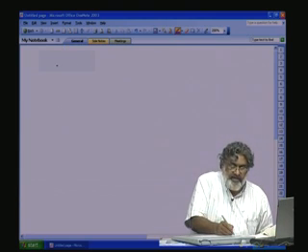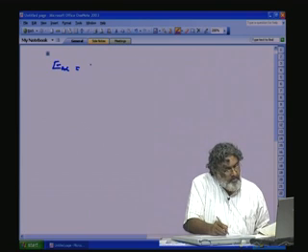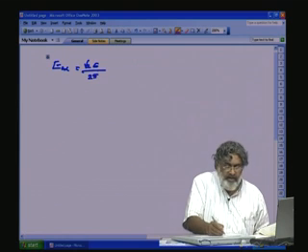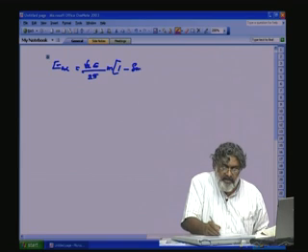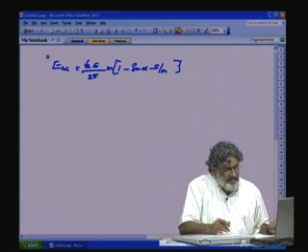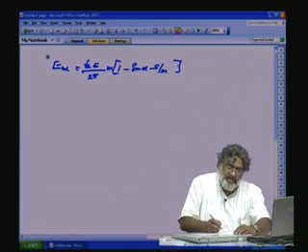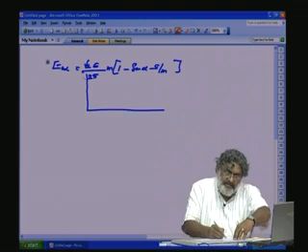From the previous equation, E0 alpha will be equal to root 2 E divided by 2 pi into m into 1 minus sin of alpha minus pi by m. For the 3-phase case, we put m equal to 3. So, the curve will approximately be something like this.